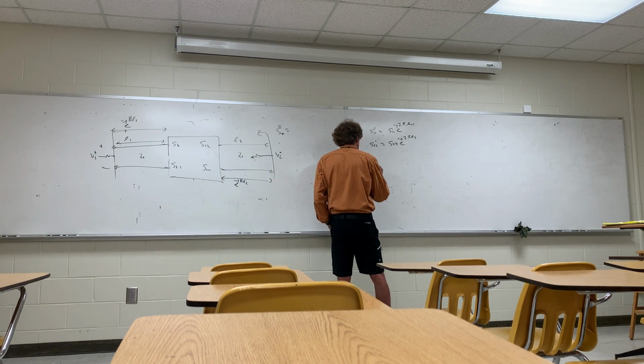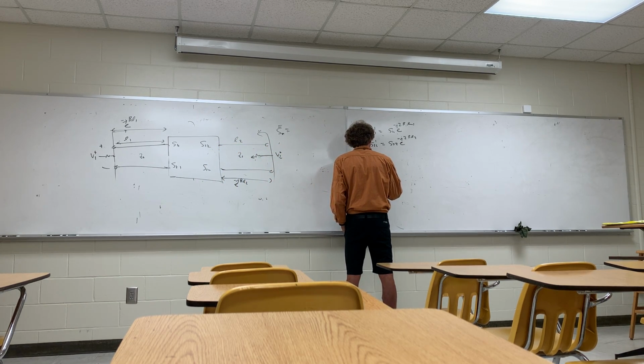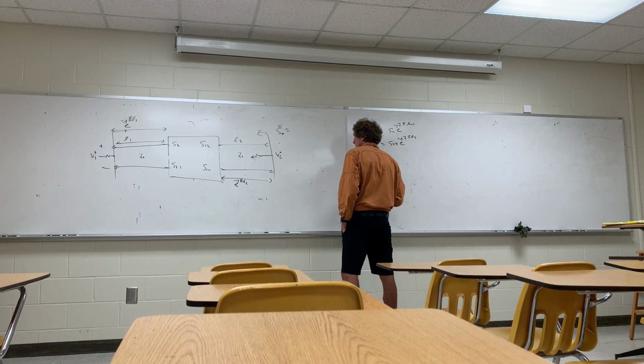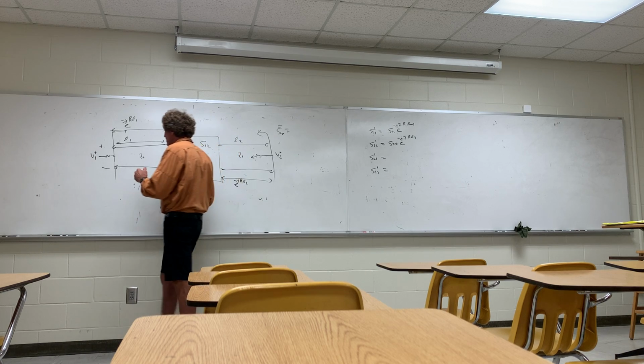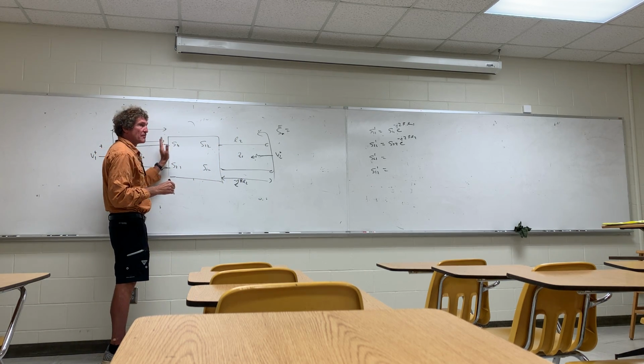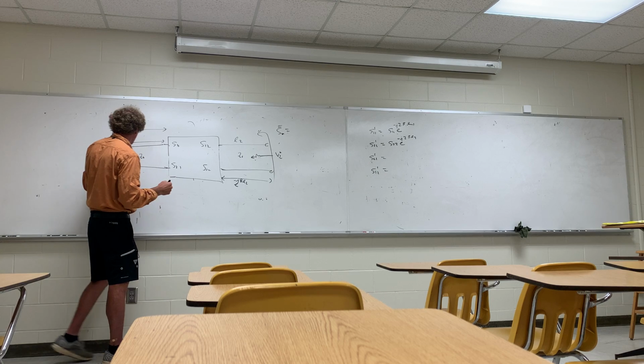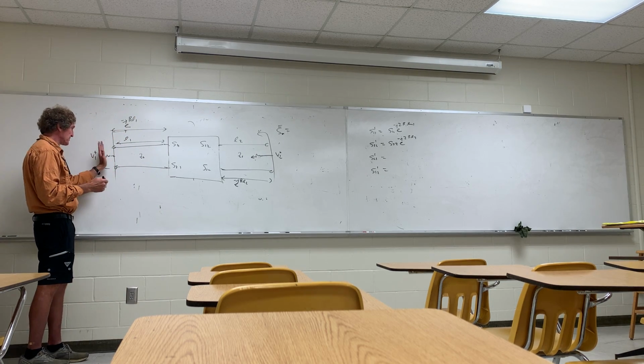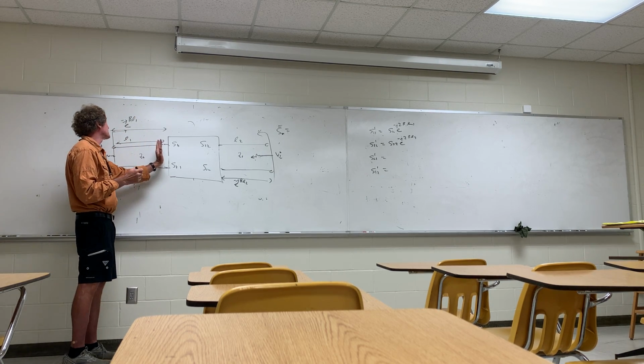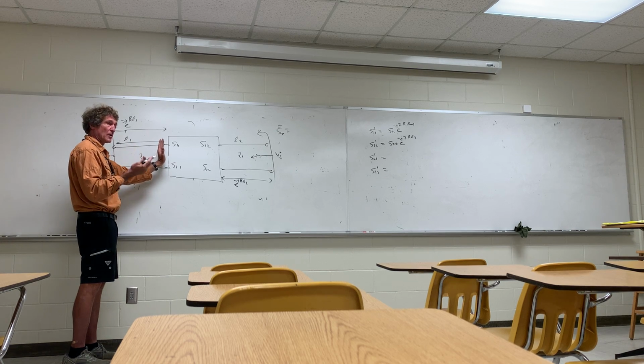Now when you look at S21 or S12, a shifted plane, come over here and just think about it. Normally, right here, V1 plus, right, times S21, right, is going to be V2 minus. Do y'all follow me on that? That's what's coming out of the port. But now, what's coming into the port, if I start here, here's V1 plus, I get phase change e to the minus j beta L1, right?